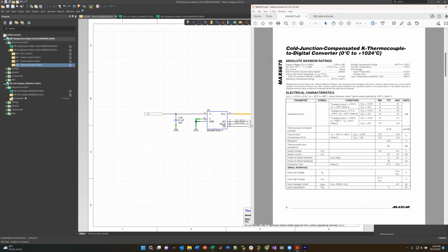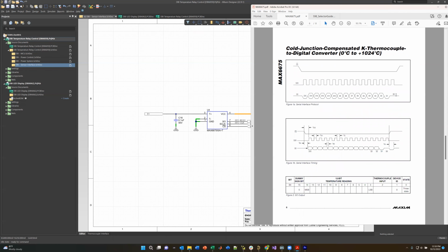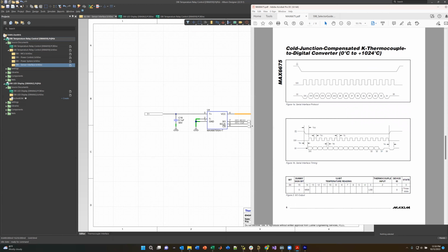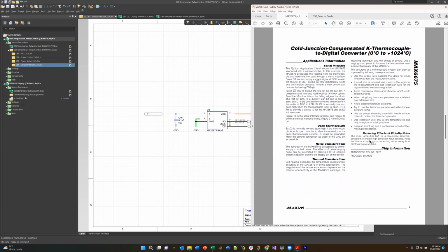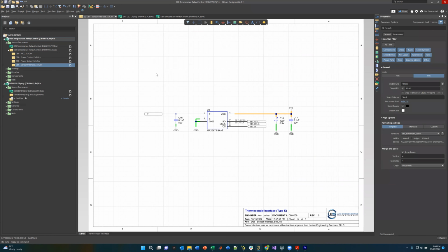It's 12-bit resolution. There's all sorts of programming information. How the data comes in is the SPI interface. The chip select here, we clock the data out, and there's 16 bits of data that we read. In fact, this data will even tell us whether or not the thermocouple has been disconnected. It's an excellent chip for this, by the way. So if you're using any thermocouples in your future projects, this is the chip to use. It's actually not a very expensive chip either. So we have that. It's a simple one-page schematic, and we're done with this page.